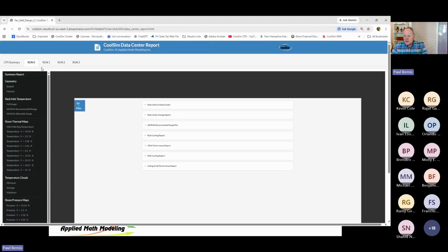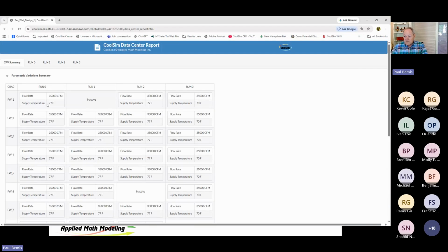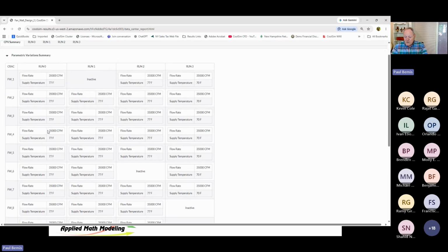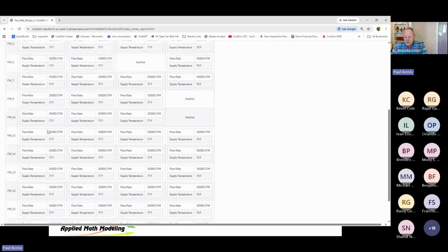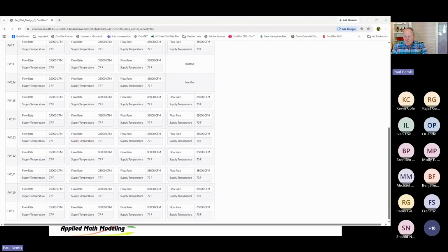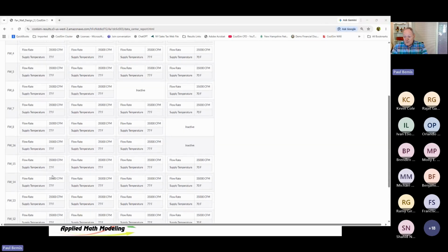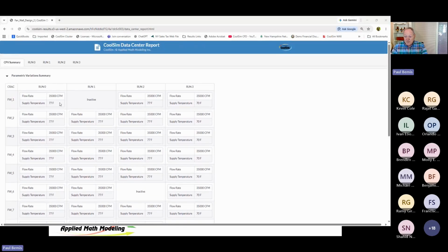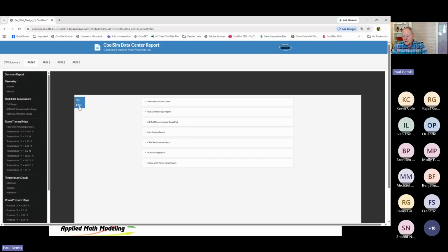First of all, again, let's look at my summary. And in my summary, I've got everything running. Everything's running at full speed. And I'm supplying at 77 degrees Fahrenheit. Now that's pretty high. Remember, my upper number is 80.6. So that's pretty good. I'd love to be able to supply at 77 if I possibly could, because that'll make my cooling systems much more efficient. Let's go take a look at run 0 and see what we find.